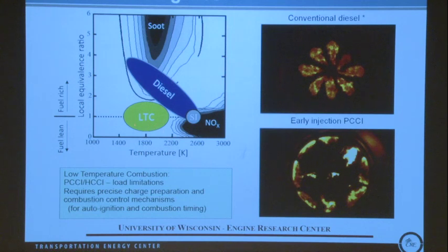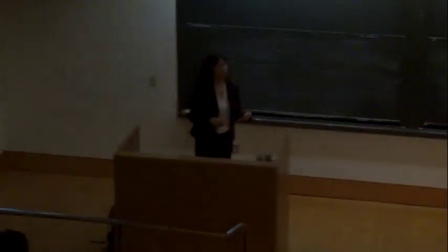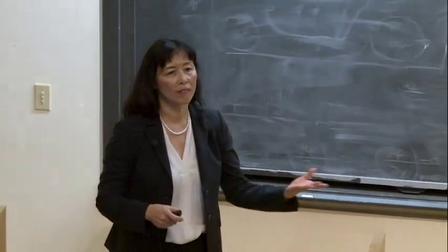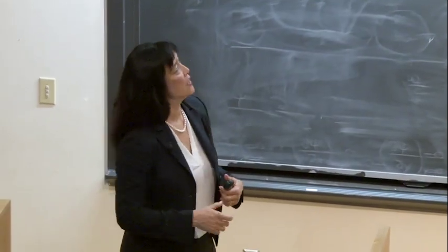When you burn under HCCI, there ends up being lots of issues with variations in load. So if you're burning under low load, you have problems igniting certain fuels. You're burning high load, you want to avoid high cetane fuels that would go off and lead to engine knock.